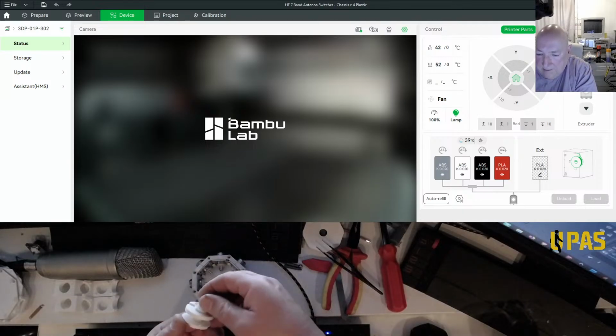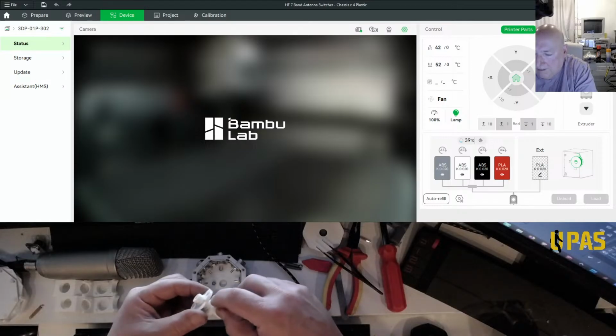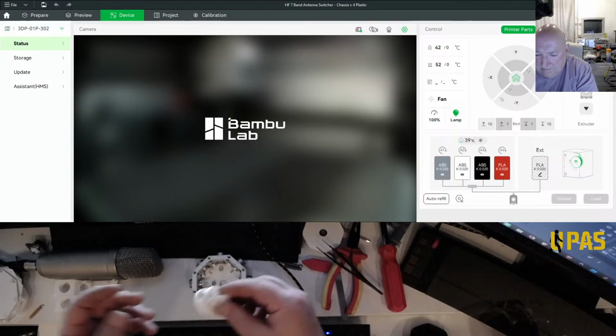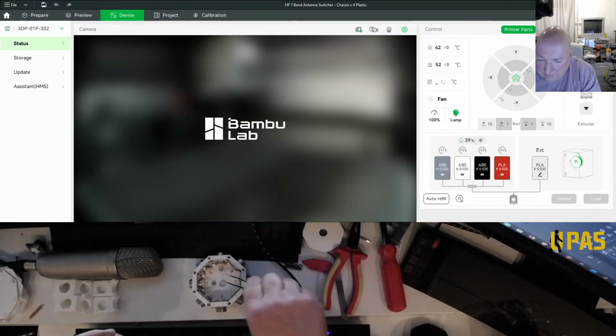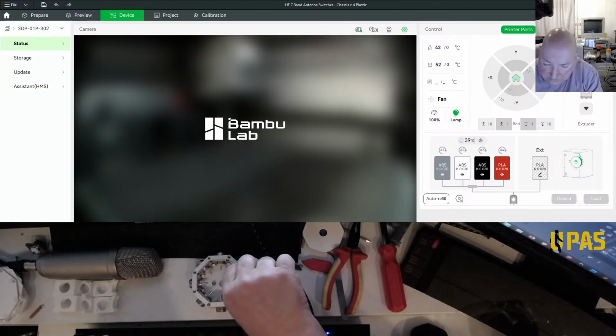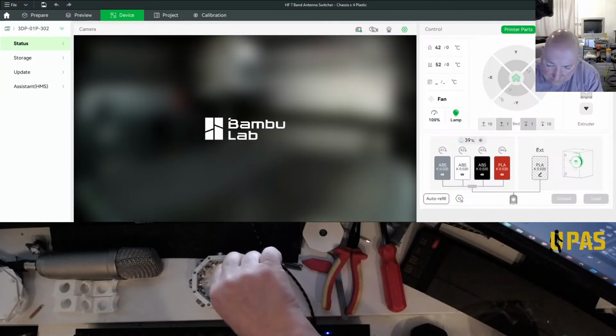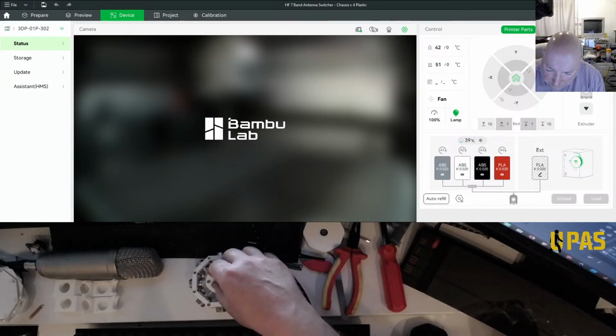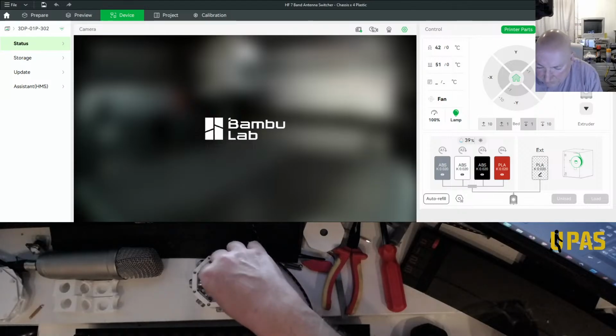Okay, so you can only just see where the wire needs to go, right in there. So to solder that on, you will need to take it apart. Now I just want to see if it touches, if I can stop the bearing from spinning around. Right, so I'm going to put this back on there. Just move it to the side, push it in the shaft.